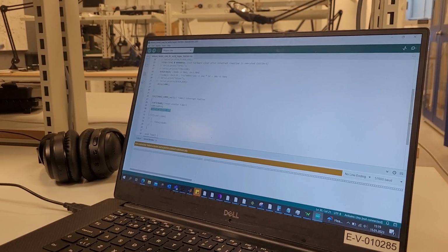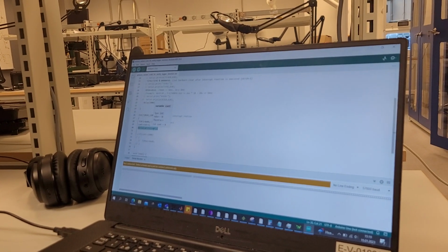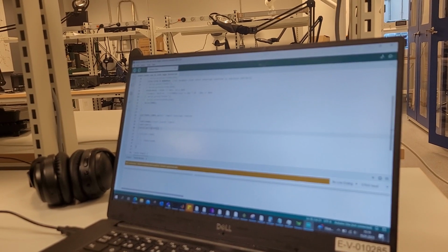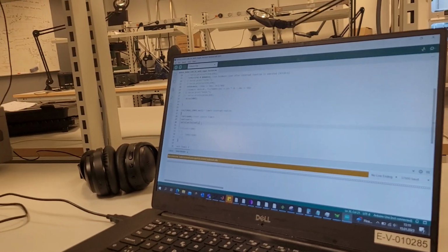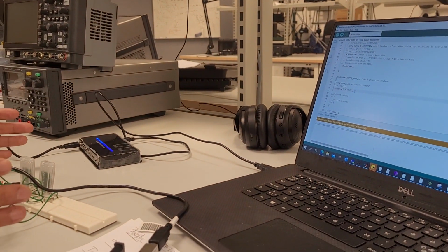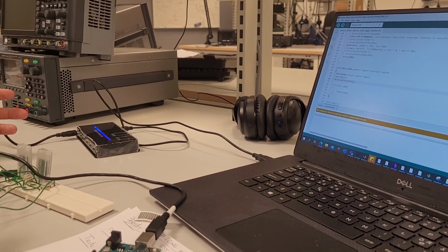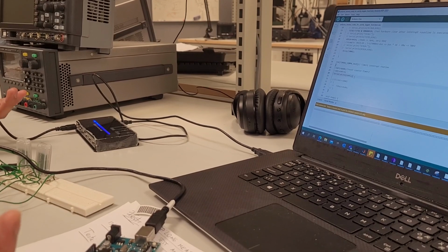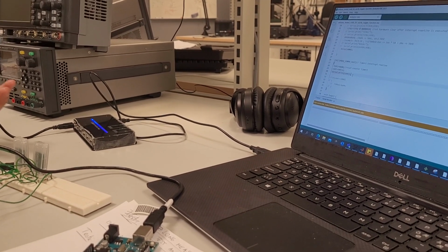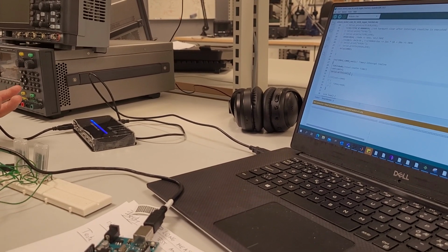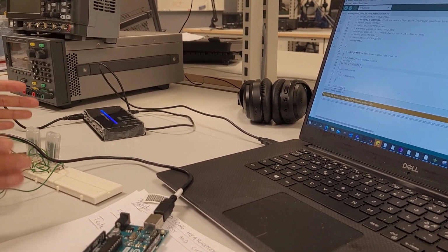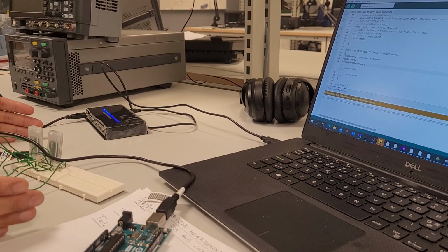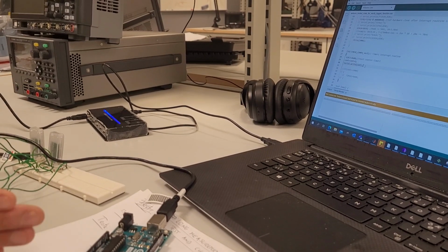And the number has 8 bits, and it follows the protocol called UART, which means it is an asynchronous protocol, used when you don't send the clock. Usually, to understand the transmitter and the receiver, you also need a clock, because you have to understand the speed of the data that is coming. This protocol does not need the clock, but you need to fix some rules which identify when the message starts and when the message ends.